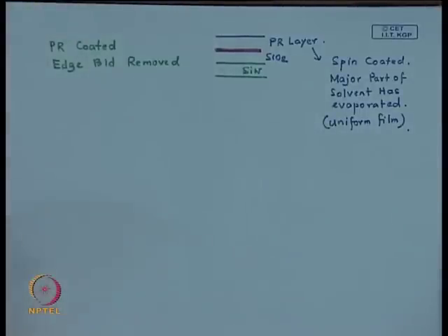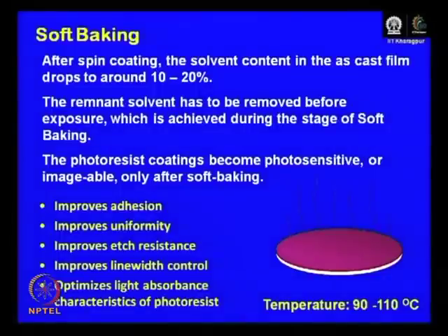If a significant amount of solvent is present during exposure, that is going to affect the photosensitivity of the layer or subsequent stages. That is not desirable at all.